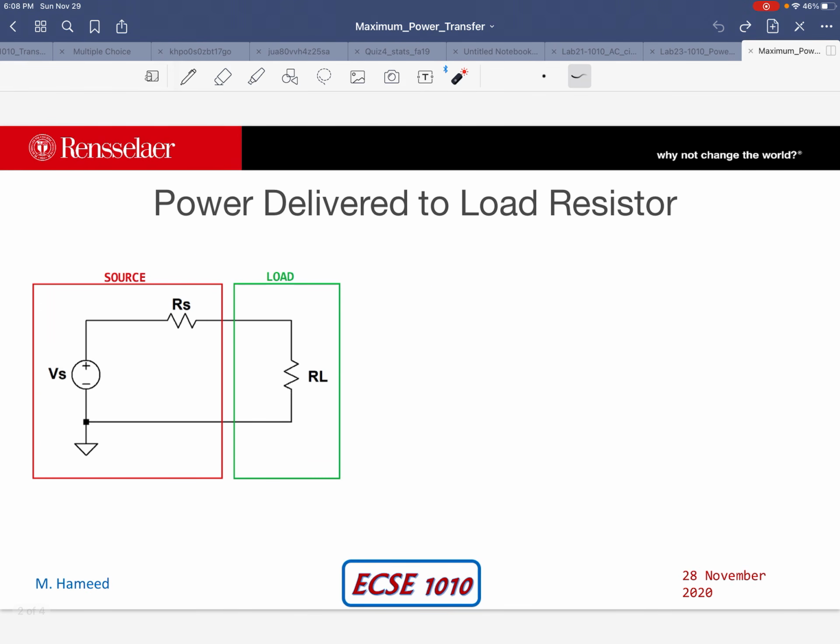On the schematic that is shown on the slide, we have a source that is put in a red box right here. It has a constant voltage source Vs and a series resistance Rs. That's our source. And for the load, we have connected one load resistor RL. What we are going to try to do is see what is the power delivered to the load resistor first, and then later we can maximize this power.